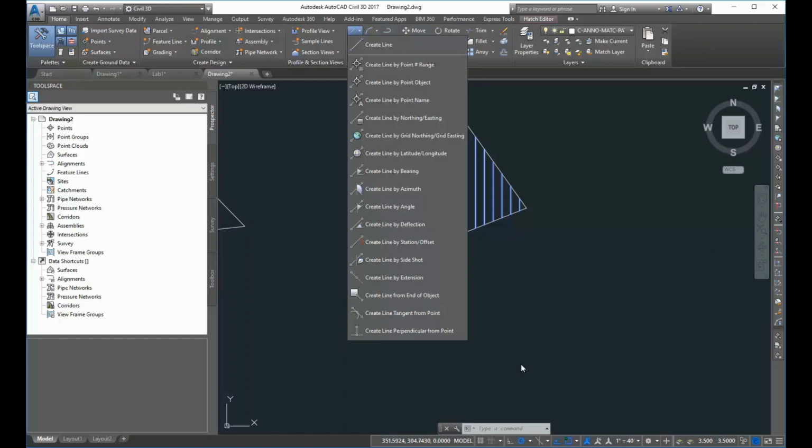Then hit zoom extents so you can find where you are on the drawing. That gets you a drawing in the appropriate coordinate location, and then you can snap to the end of that line, the first coordinate, or the lower left end of the line, and start doing a drawing by bearing and go around.